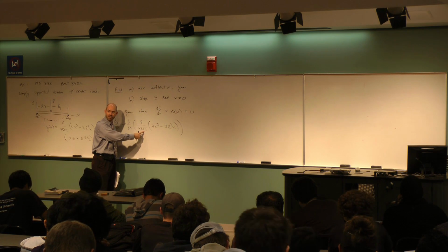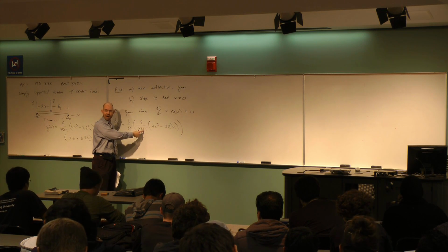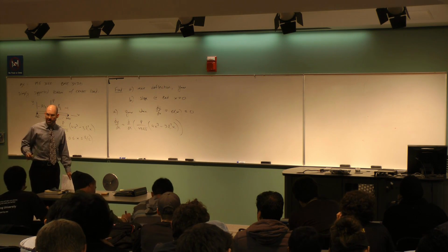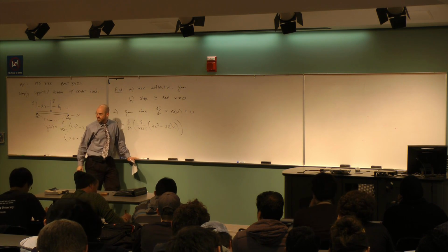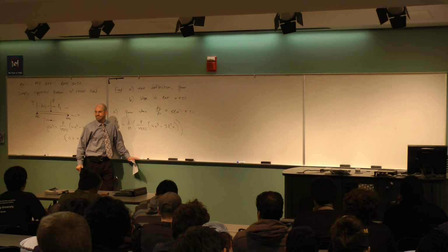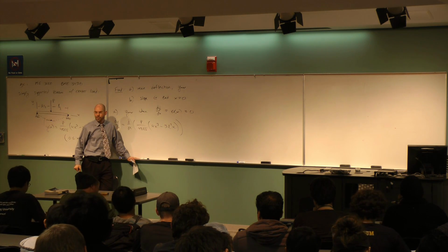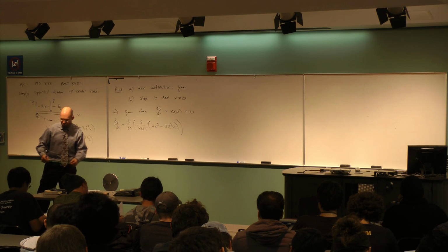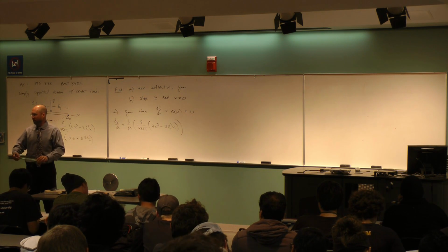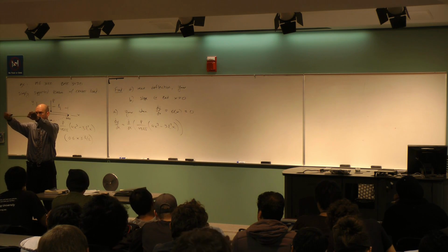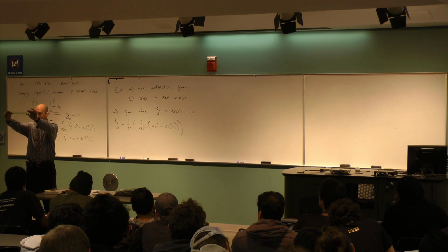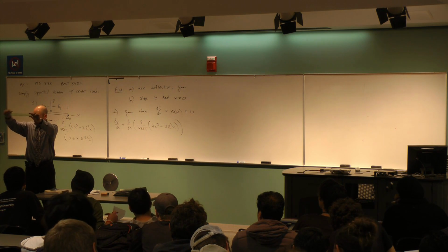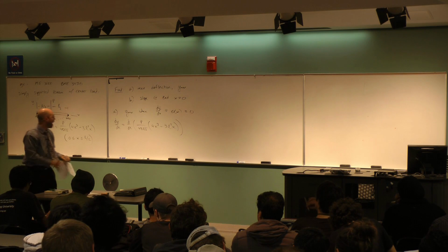Anybody recall what is this E and I here? Elastic modulus, the E, right? Is this thing made out of plastic or is it made out of aluminum? That affects the E. And then the I is affected by what? What's that I called? Anybody remember? It's the second moment of area, also called the moment of inertia, but that's geometry. It's got nothing to do with the material, right? So a beam this way has a pretty flimsy I. If I take the same beam and go like that and try and bend it, I can't even bend this thing. The I is a lot bigger because I'm trying to bend it about the height instead. So the actual shape of the cross section itself, the geometry, changes the I.